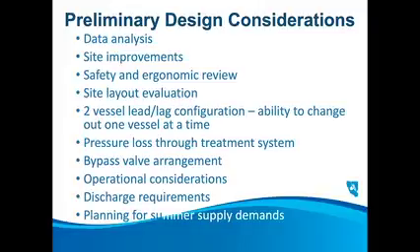We also had to look at pressure loss through the treatment system. So we really had to make sure that we understood what the constraints were with the well pumping and all of that. And then we installed a bypass valve arrangement so that as we were coming up to the implementation of when we had to take our first samples, we were bypassing treatment until the treatment was constructed, and then it was connected into our system.